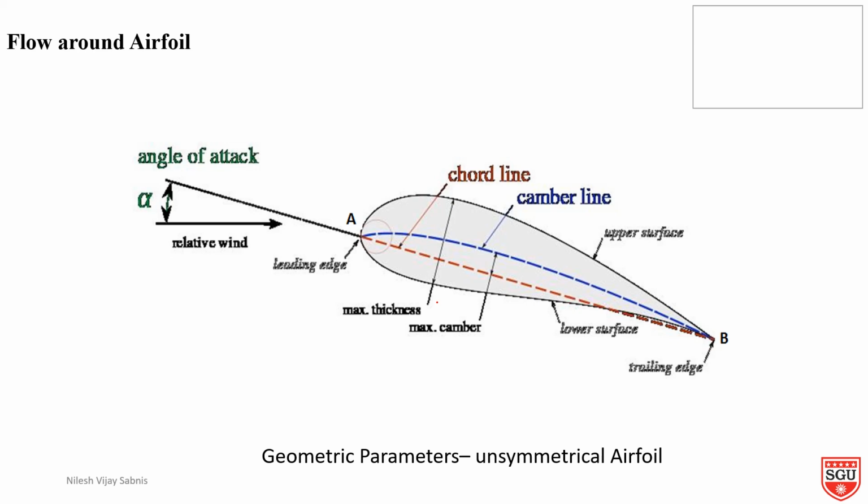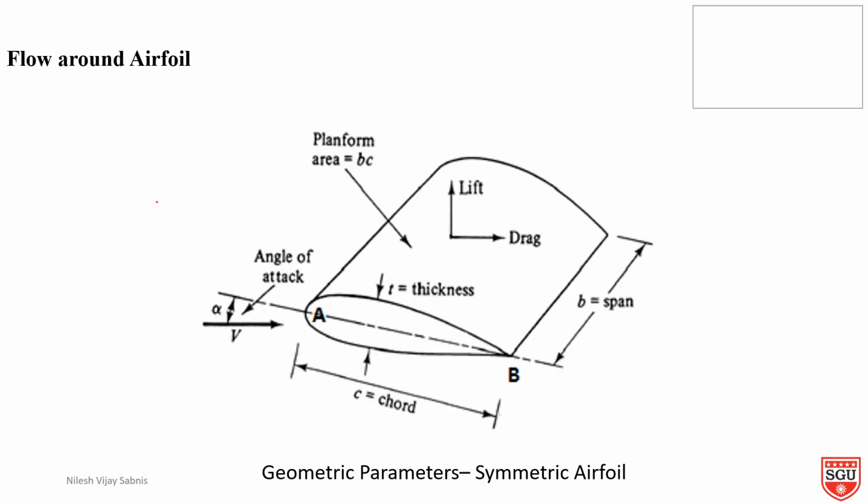When we consider an aerofoil, there are some concepts. Aerofoils are streamline bodies which may be symmetrical or asymmetrical. The aerofoil shown here is unsymmetrical. It is characterized by its chord length, angle of attack alpha, which is the angle between the direction of flow and the chord line, and the span L of the aerofoil. The drag force on the aerofoil is always small due to the design and shape of the body, which is streamline.